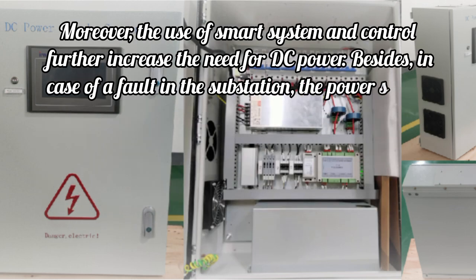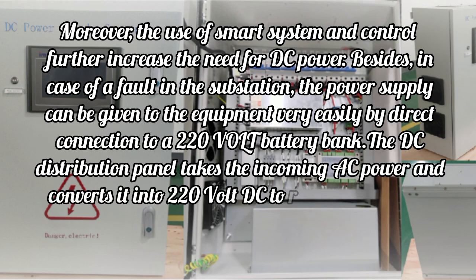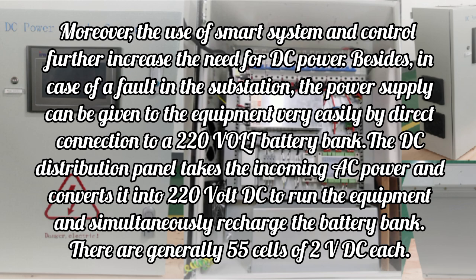Moreover, the use of smart systems and controls further increases the need for DC power. Besides, in case of a fault in the substation, the power supply can be given to the equipment very easily by direct connection to a 220-volt battery bank. The DC distribution panel takes the incoming AC power and converts it into 220-volt DC to run the equipment and simultaneously recharge the battery bank.